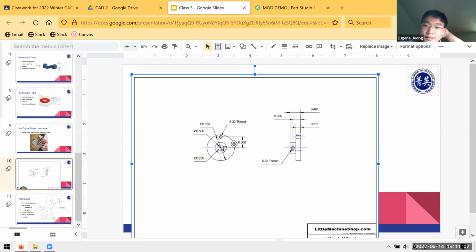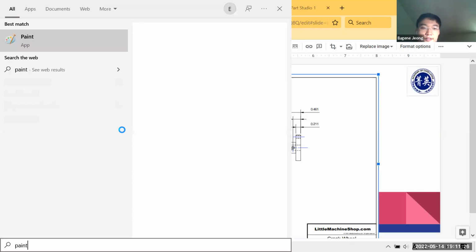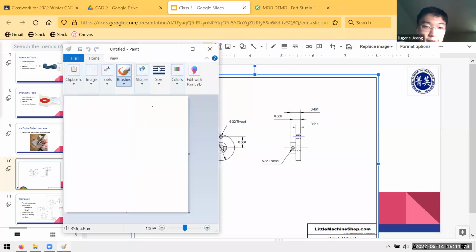So as I talked about, there are going to be 2 ways you can approach this. You can either extrude 2 circles, or you can revolve one L-shaped piece. Let me illustrate what I mean. You can extrude your 2 circles, which hopefully you're aware of how to do.